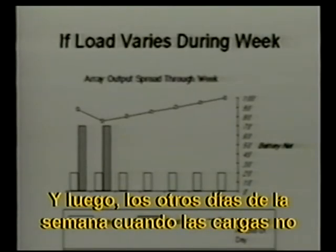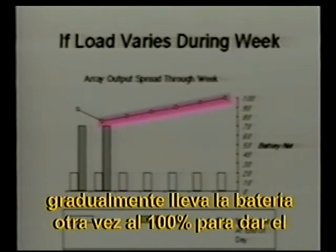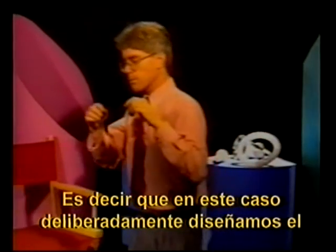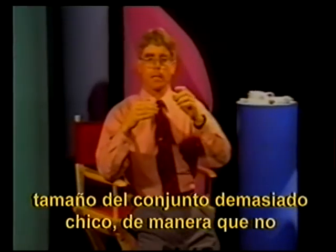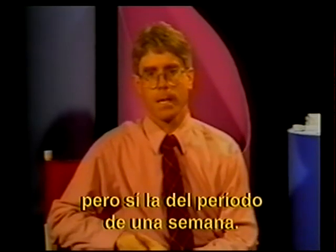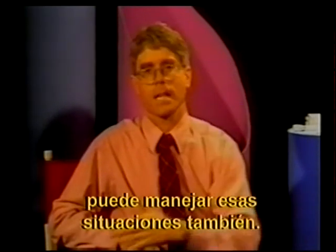And then during the other days of the week when the loads aren't operating, the array operates just like it's supposed to and gradually brings my battery bank back up to 100% so that I can have another weekend's worth of operation. So in this case, we're deliberately sizing the array too small so that it doesn't meet the daily load demand, but it meets the load demand over a period of a week. We've created for you a separate sizing form that can handle those kinds of scenarios as well.